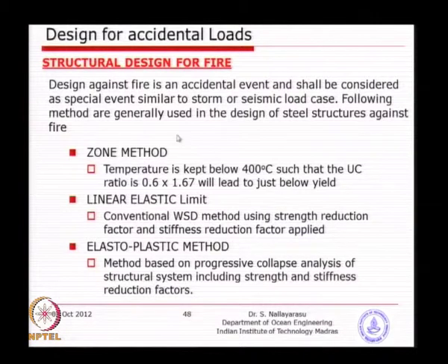The linear elastic limit, as we normally do in most of the design in the last several years, is just to replace the yield strength by the actual reduction factor. So, if you have 0.6 Fy, you replace throughout and replace the modulus of elasticity corresponding to either the tangent or the initial modulus. This is what has been practiced by almost all designers in the industry for so many years, because it is quite easy.